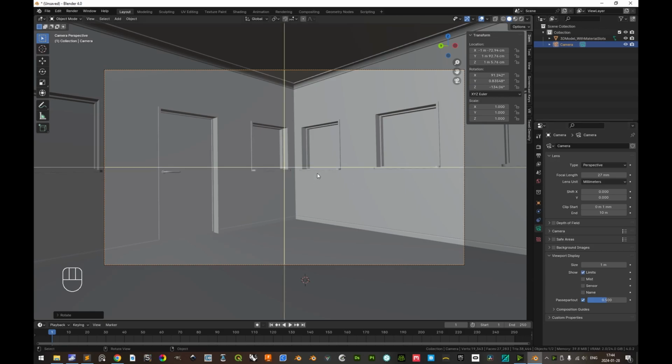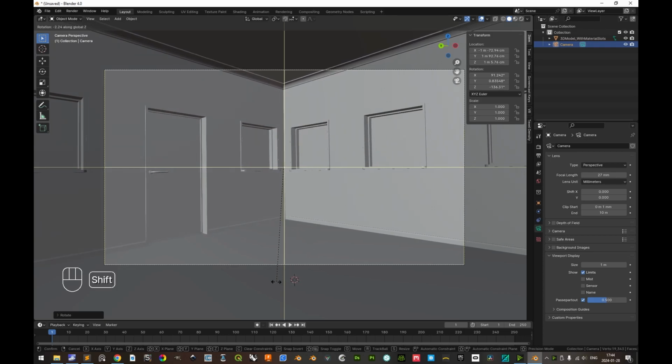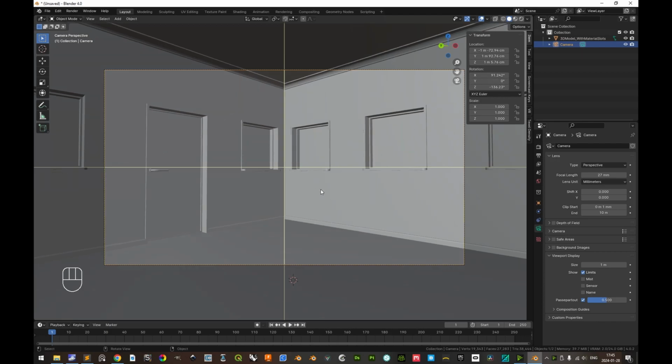And then we can simply do rotate with R and along the global Z. And then we can see here if we can make it like this perhaps. We see that we have a slight Dutch angle, so here in the item pane we can just reset the Y rotation to 0. Great. And now we can rotate along the global Z-axis and have a completely straight line there.